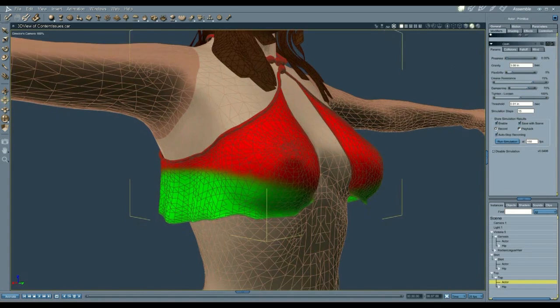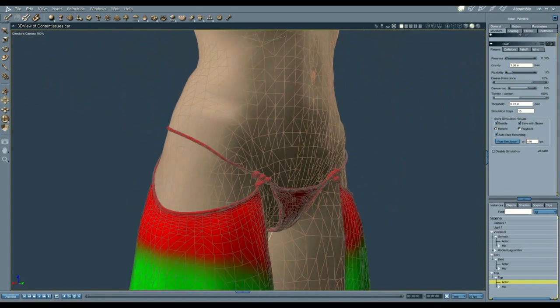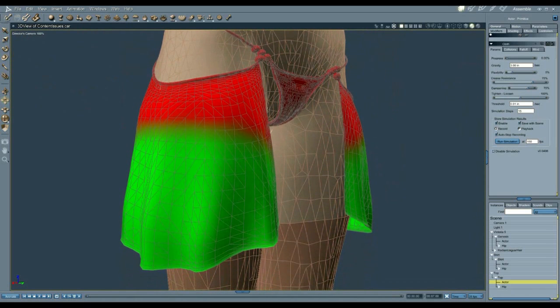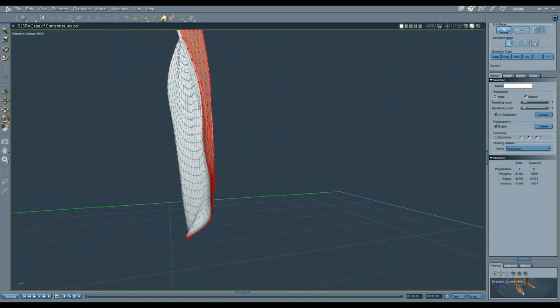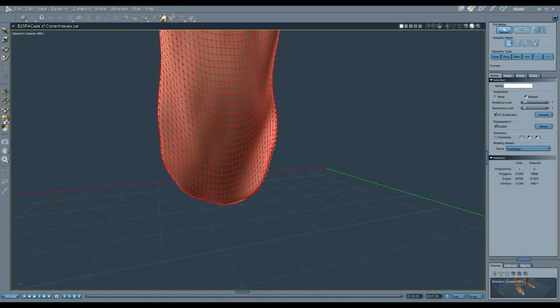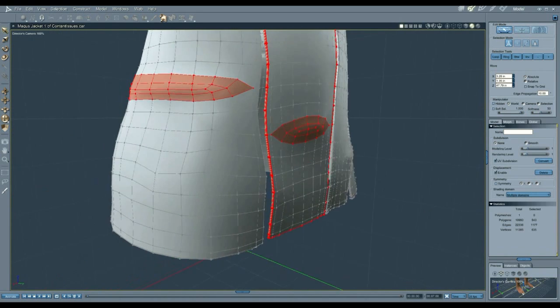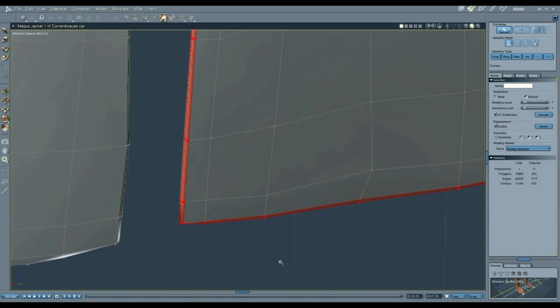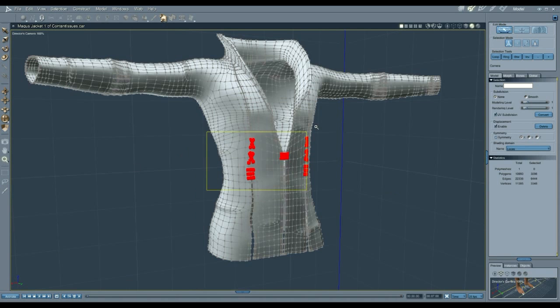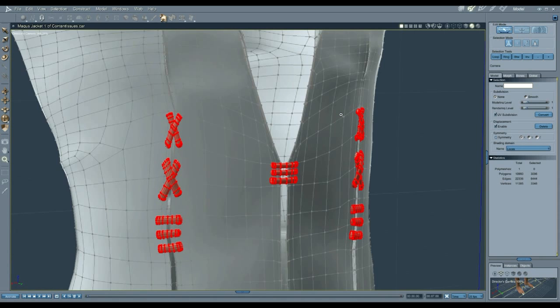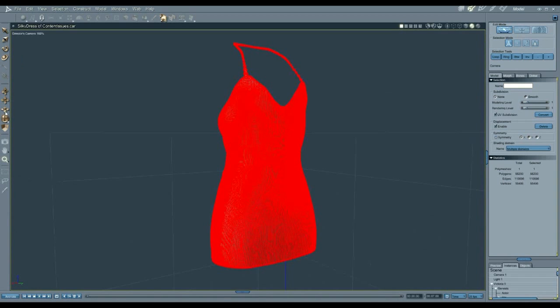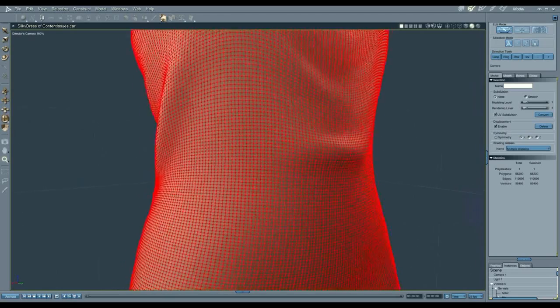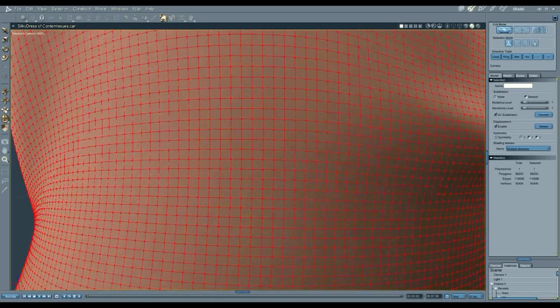Clothing parts suitable for dynamics need to have a simple and regular mesh, especially for self-collisions to work. A thickened, double-sided mesh will have trouble with self-collisions. Conforming costumes typically have lots of modelled detail, including hems, laces, loops, and pockets. These will all fall off during the simulation. Conforming clothing often comes with a high-resolution mesh, which will be too slow to work with.